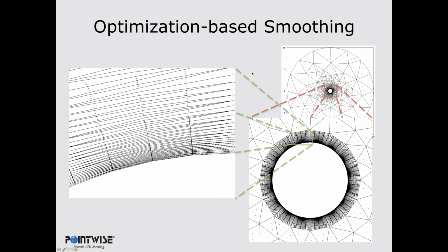So here's an example of this being applied to a triangular mesh for 4th order elements. It's a circle within a circle, and then there's a highly refined region near the inner circle with large, long triangles, and the figure on the left shows the elevated mesh. As you can see, there's dots that are the locations of the interior nodes of the higher order element, and the mesh is conforming to the boundary and then naturally gradates away from the surface in a nice fashion.